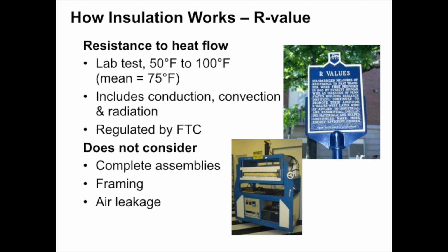Finally, it's really important to note when we talk about R value that it was never developed or intended to account for things like air leakage or framing elements or complete building assemblies, right? It's really just meant to be a tool to compare materials.